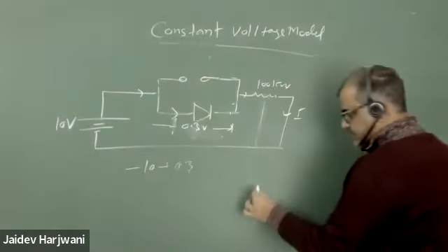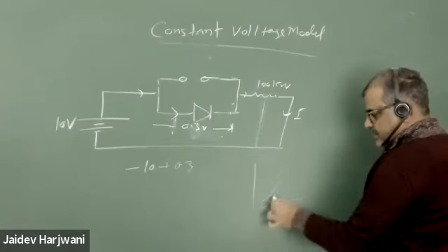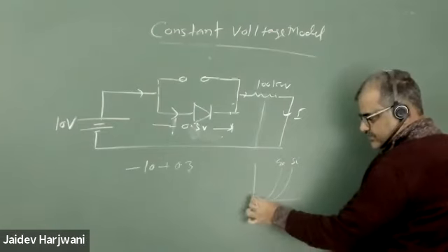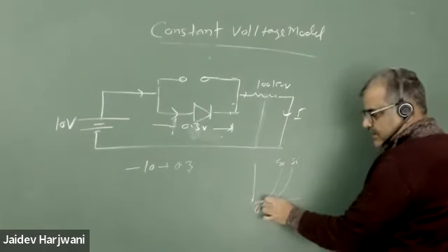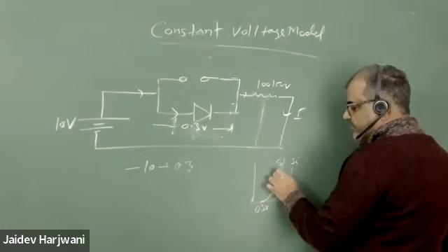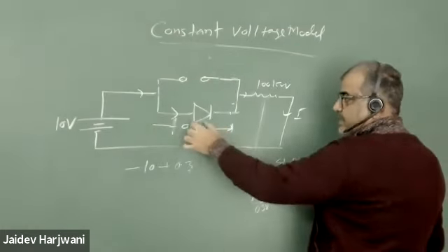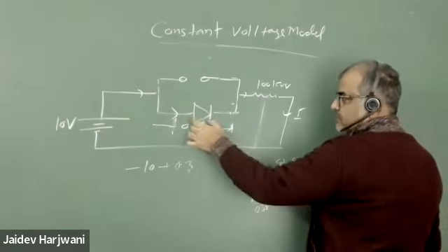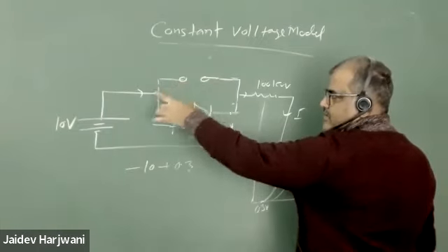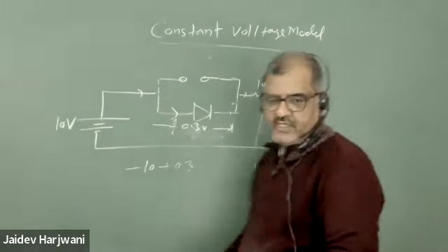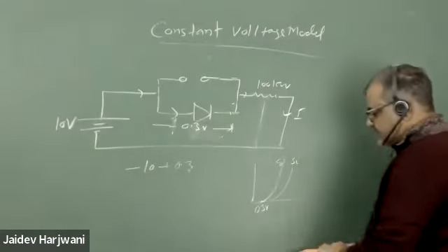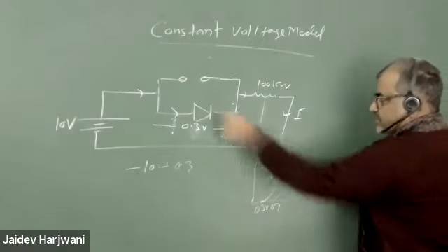If you see the IV characteristics of germanium and silicon, so germanium is this one. Once it goes to germanium, current starts flowing, and any amount of current will flow here, if it is not burning. Once this is 0.3 volts, that becomes fixed here, and once 0.3 is fixed here, it cannot rise to this one. The current will choose the path where there is the least resistance. So it will go through this one because your silicon is 0.7, and current will not go from here.